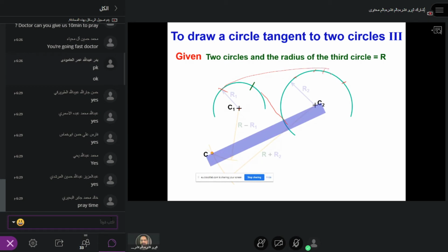This is also a tangent. This is also a tangent. It's all a tangent. Anywhere you can draw. Do you understand what I'm saying here? These all are tangents. So by using this theory, we are trying to design the cams. That's why, tangent to tangent, you have to join it. So you have to identify tangents, several methods.